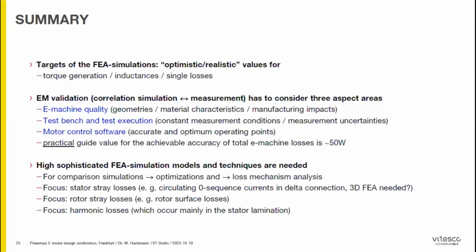Also, further stray losses should be checked. Rotor surface losses, I heard this is already in planning or in doing or existing. And I would say everything which is going with eddy currents should be done with 3D. I would say eddy current losses doing with 2D, I would not be confident about this.